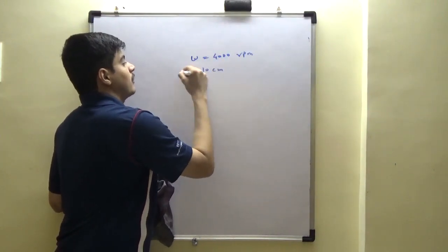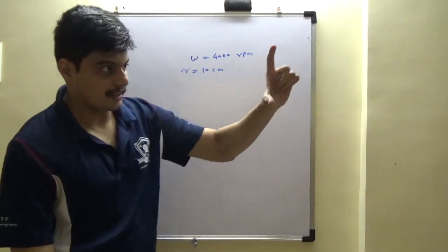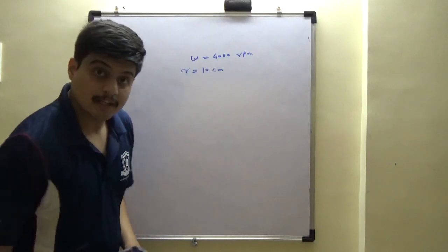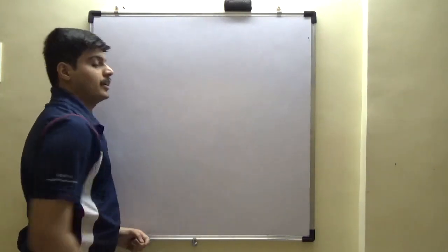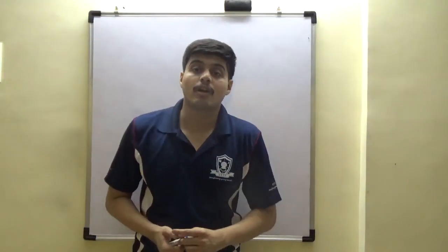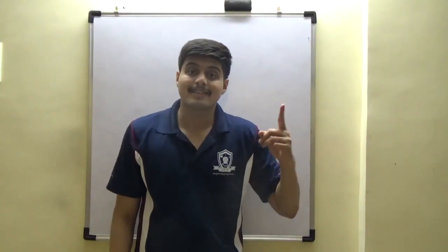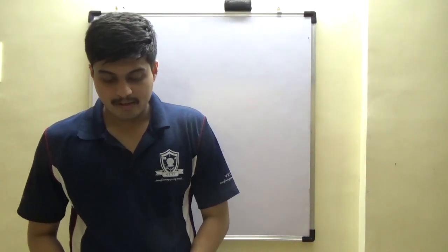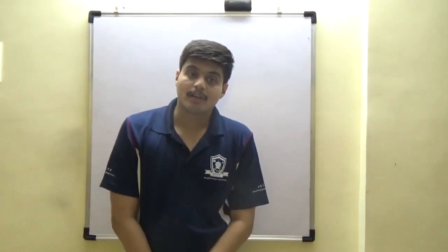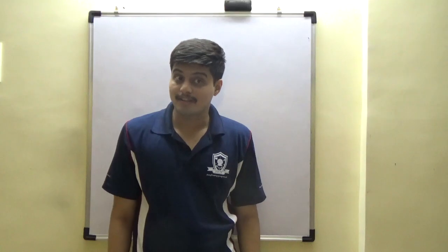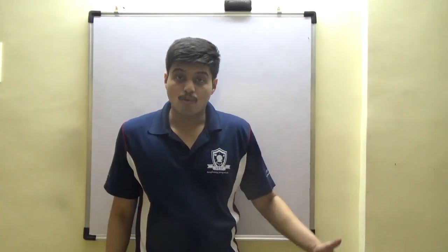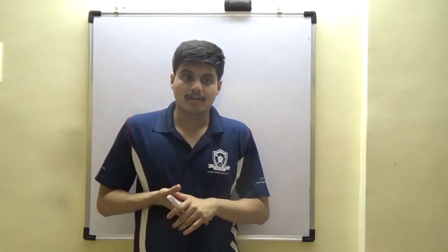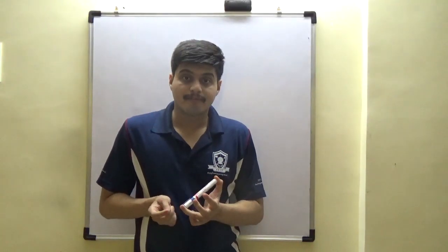And 10 centimeter radius, which is typically the blade height, right? 10 centimeters, which means the speed is very, very high. It is a single stator rotor combination that makes the difference. The CZ that you saw was 160, very high axial velocity. So just by having one stage is not enough.